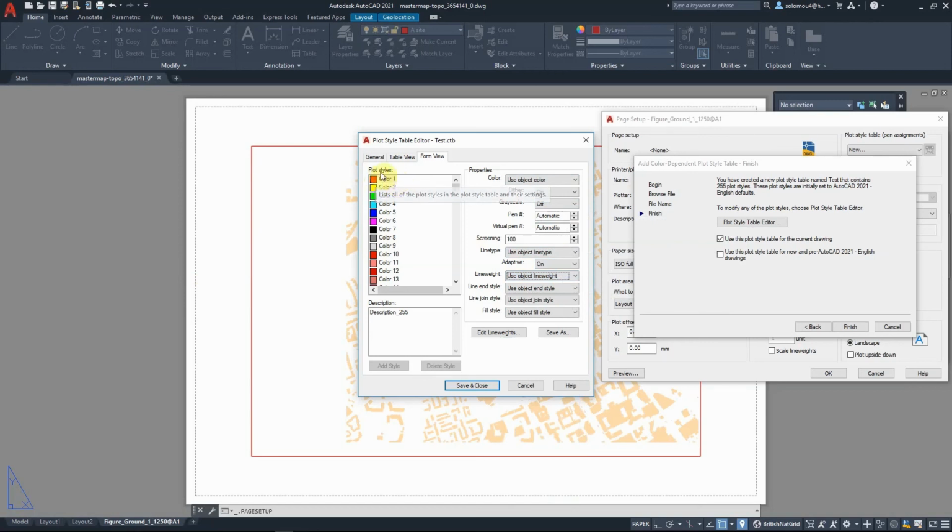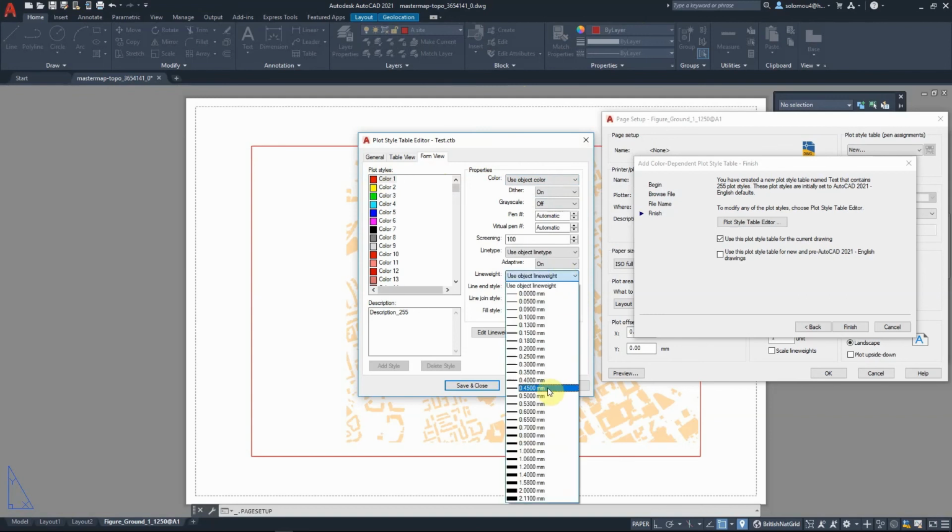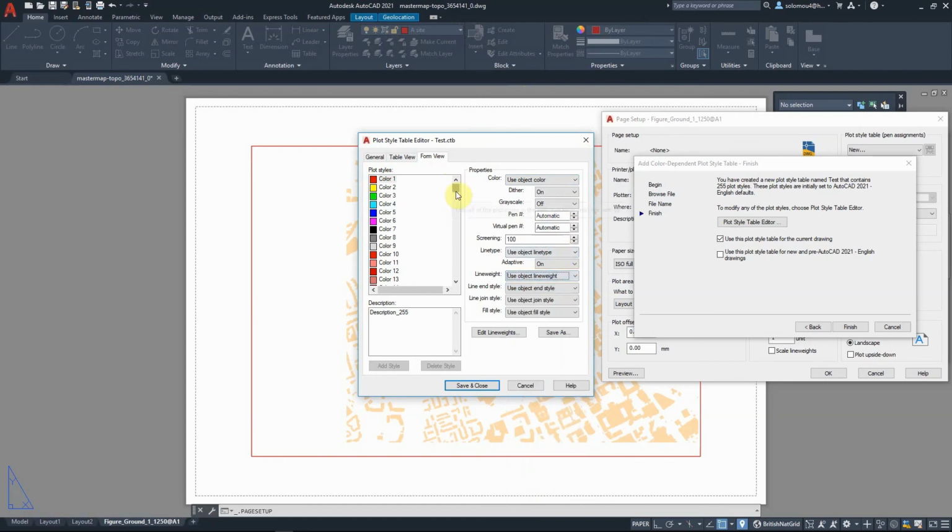So they would use this particular layer called external walls that will have the red color, and because their plot styles has red as being, let's say, a line weight of 0.30 or 0.40, they don't have to consider thickening up the lines in their drawings. It automatically happens through the plot styles every time something's printed. It doesn't have to be printed in red.